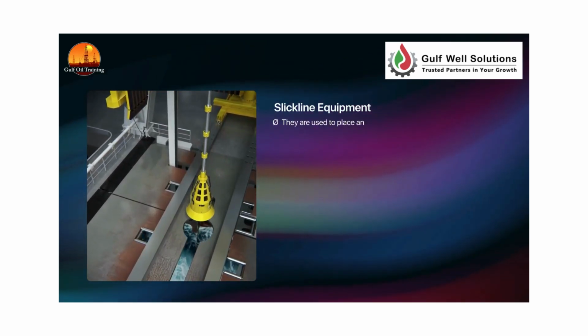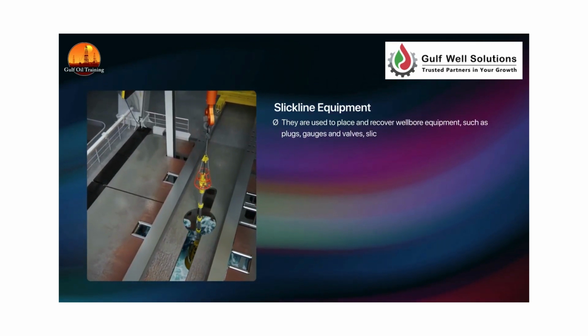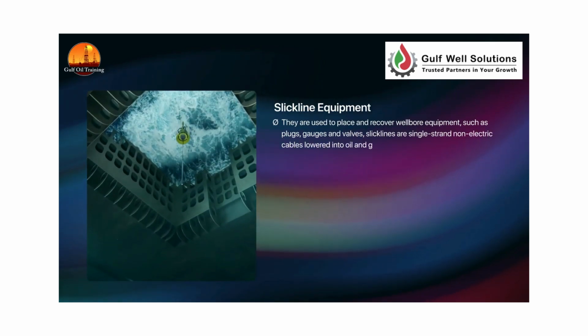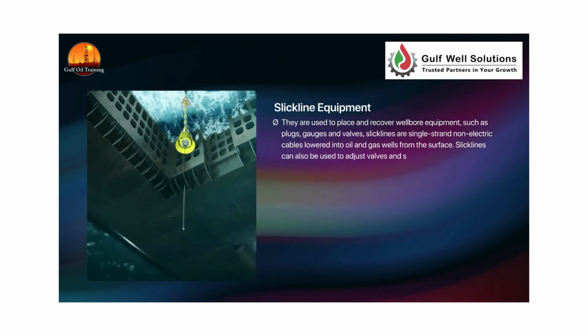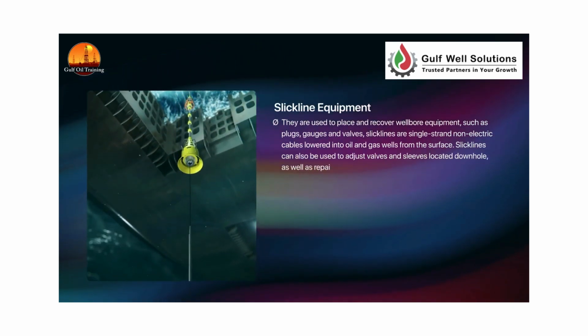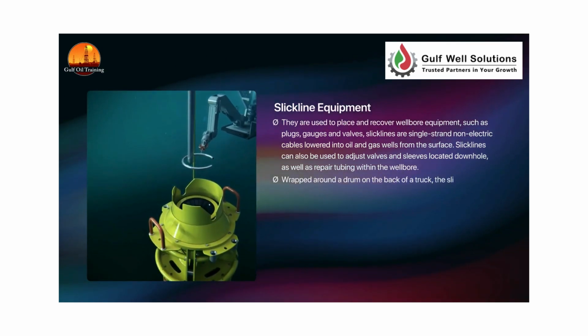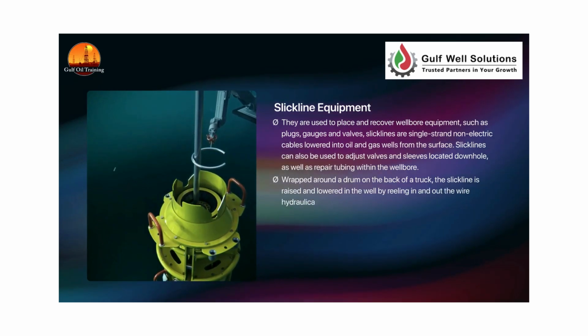They are used to place and recover wellbore equipment, such as plugs, gauges and valves. Slicklines are single-strand non-electric cables lowered into oil and gas wells from the surface. Slicklines can also be used to adjust valves and sleeves located downhole, as well as repair tubing within the wellbore. Wrapped around a drum on the back of a truck, the slickline is raised and lowered in the well by reeling in and out the wire hydraulically.